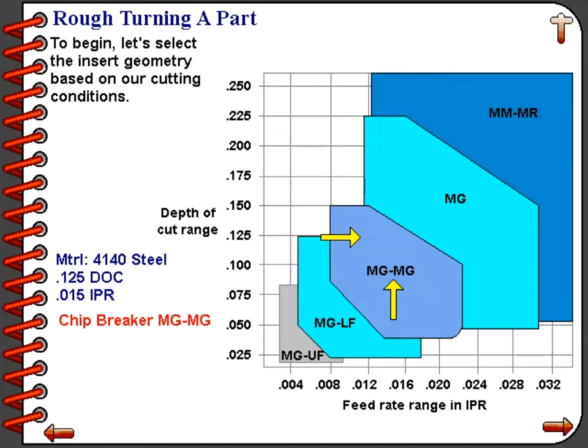While we're on this screen, we could also select our insert geometry for our finishing application, and that would fit into the category of MG-UF or possibly MG-LF. Either one would appear to work fine for a finishing application.